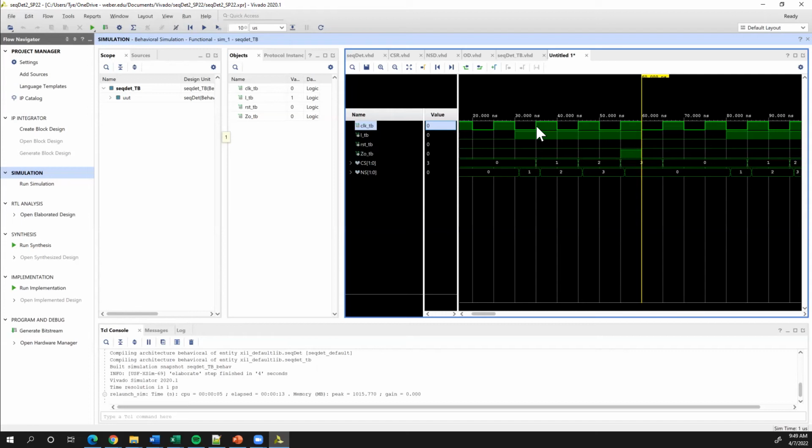We could clock it if we wanted, but this is kind of the behavior of Mealy state machines. This is kind of why Mealy state machines are hard to design, if I'm honest, because of this type of behavior, because your outputs aren't necessarily true just because you're in a particular state. It's also looking at the inputs, and the inputs can change at any point during that state, which will change your output. So there's a particular difficulty around that because your output is not even true for a full clock cycle in this case. So the Moore state machines can be a little bit easier to build.